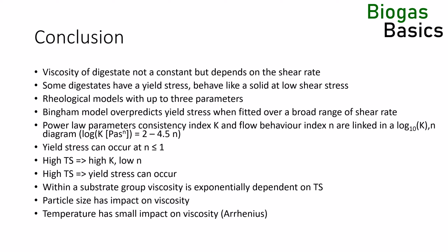Lastly, the viscosity of the supernatant plays an important role on the viscosity of a suspension. A viscous supernatant amplifies the viscosity of the suspension. This effect explains how enzymes can reduce the viscosity of digestate without reducing the concentration of suspended solids, and why the addition of fresh water reduces the viscosity further than the recirculation of process water.